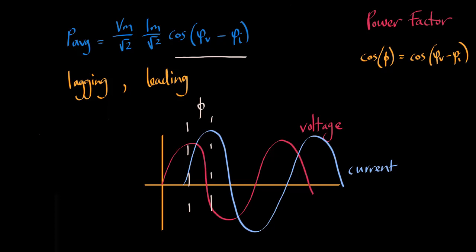Here is the phasor diagram. If you remind yourself of the phasor diagram of an inductor, you will see the positioning of the current and voltage phasors as a clear indicator that this is correct, with the current lagging behind the voltage. Please note that the reverse is true with capacitive circuits, where the current leads the voltage.